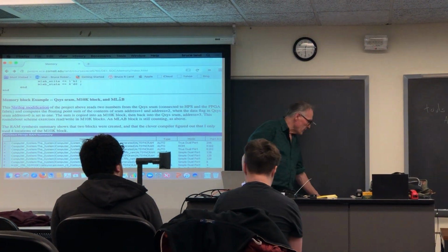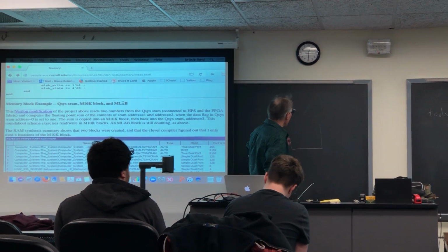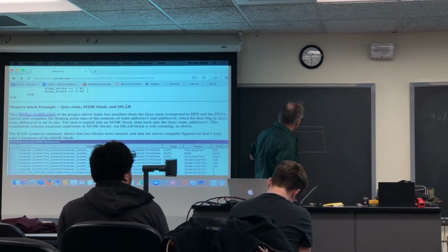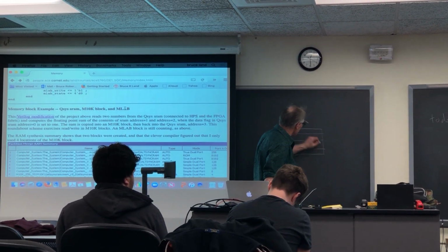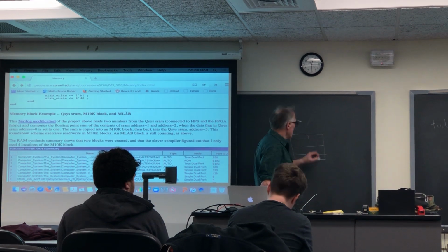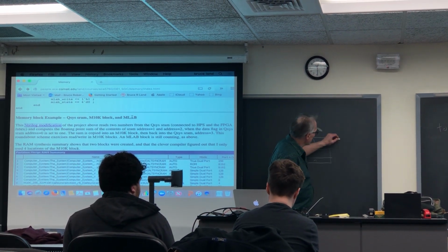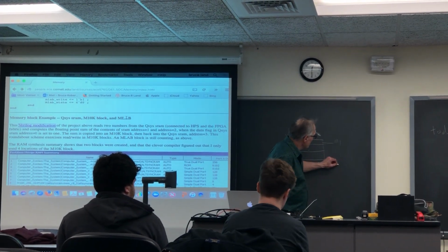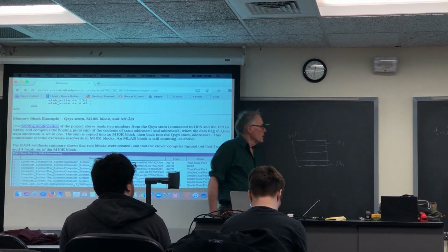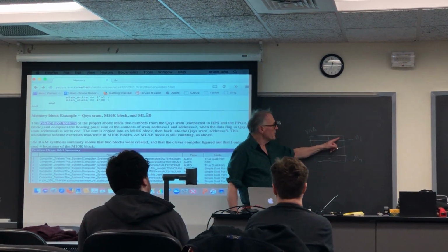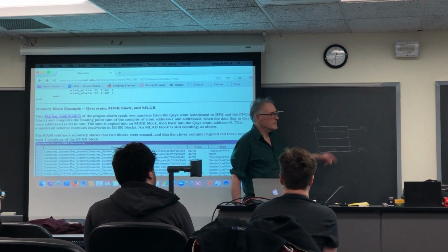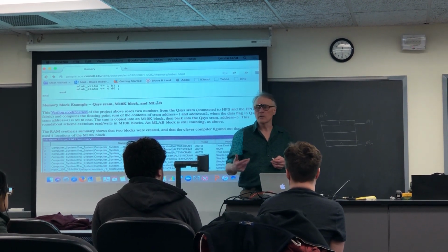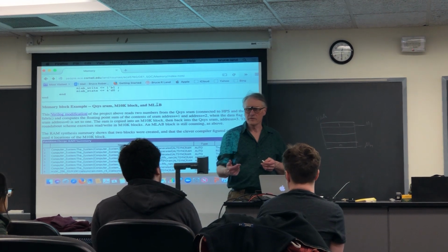So if you wanted to tile your VGA display into N solvers, each one of which had a memory block, then you would probably want to divide the screen into appropriately sized sections so that one or a few M10K blocks represented that section of the screen.